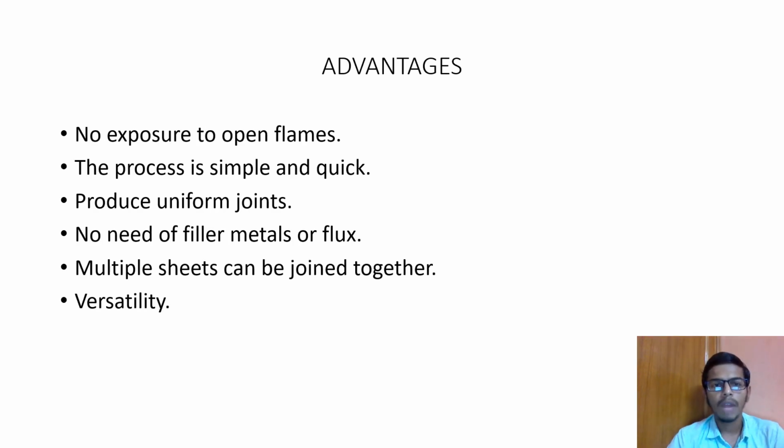Now let's look into the advantages of spot welding machine. It has no exposure to open flames. The process is quite simple and quick to complete. It produces uniform joints all over. No need of filler metals or flux. Multiple sheets can be joined together using a spot welding machine, and it is found to be versatile in many industries.